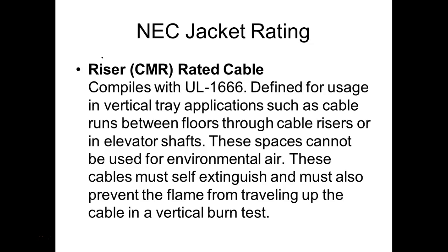Uses are in vertical tray applications such as cable runs between floors, through cable risers, or in elevator shafts. These spaces cannot be used for environmental air, which is what the plenum is. These cables must self-extinguish and must also prevent flames from traveling up the cable in a vertical burn.